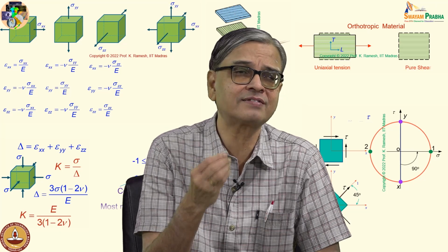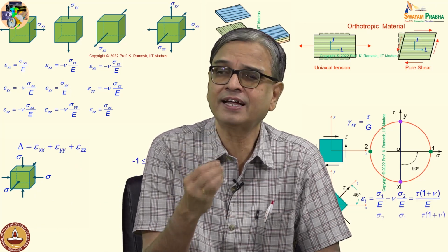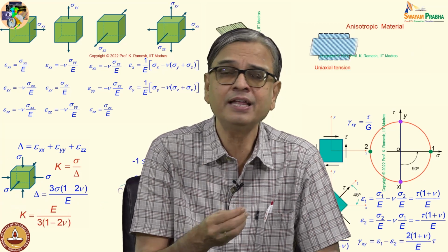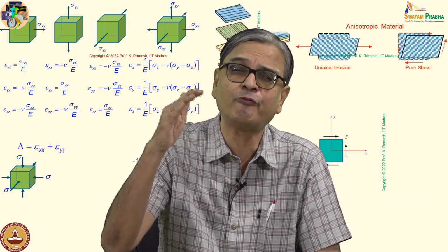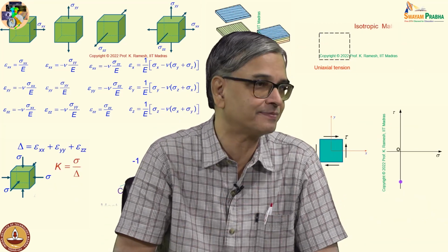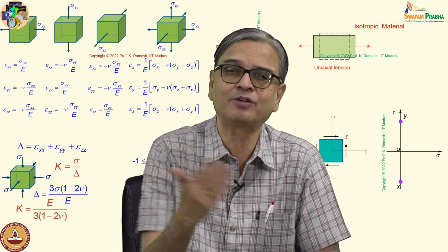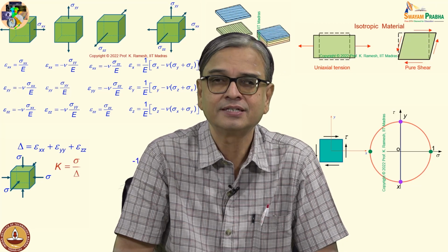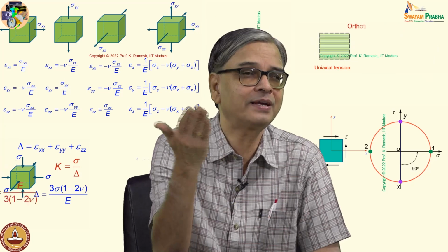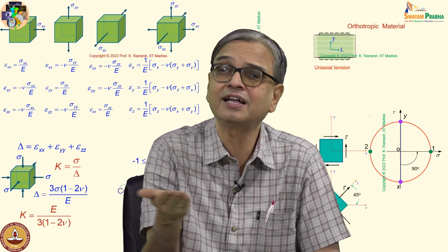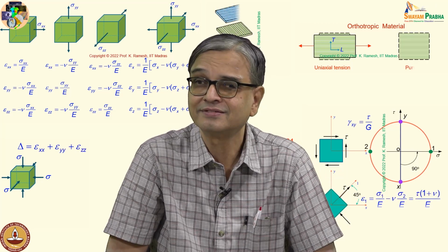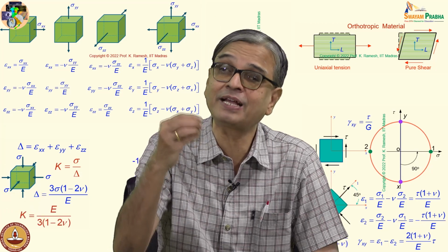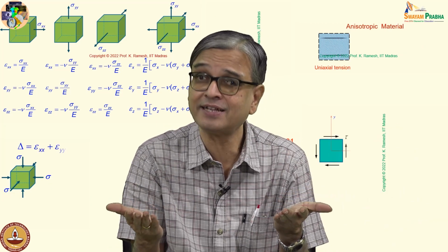And we have also seen with sufficient discussion, even though it is a convenient way to say small deformation, in reality, in many practical applications, we work under very small levels of strain in actual loading. Because everything is dynamic, you are having only fatigue loading everywhere. If you come in your car, there are many moving parts. Even if you are sitting in your chair, you get up and then come back. That means the chair is also experiencing a fatigue loading. It's a function of time, the load changes. So whenever the load changes as a function of time, the maximum load that I can apply is smaller and smaller, which you have seen by experience.